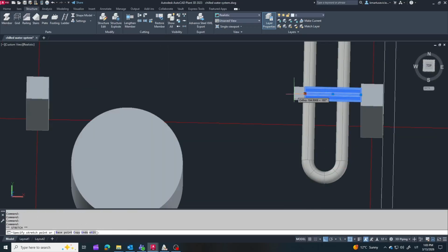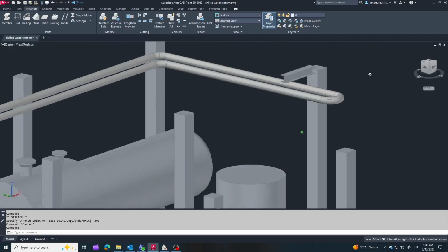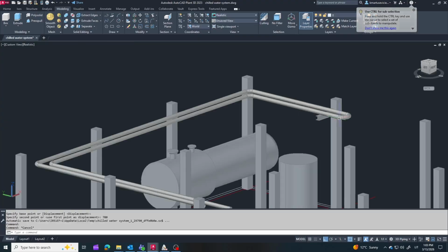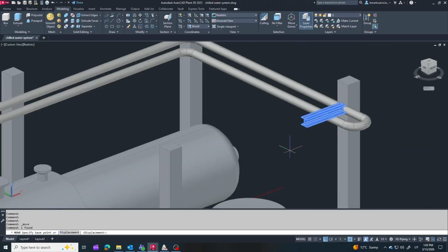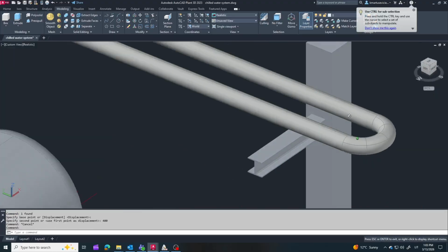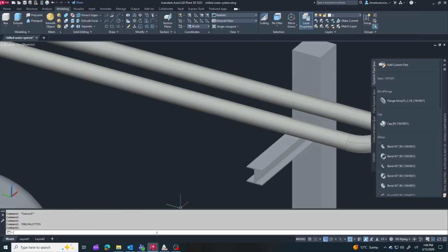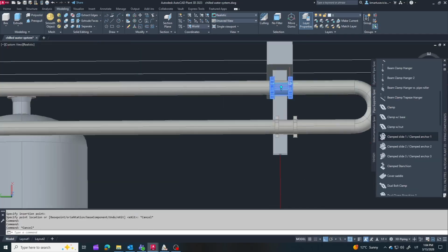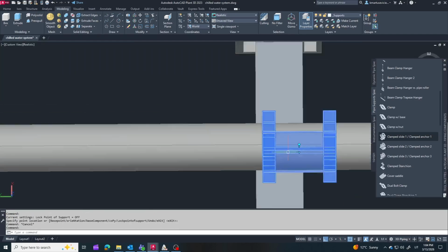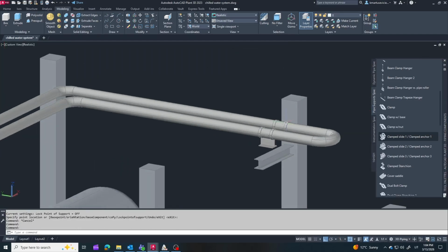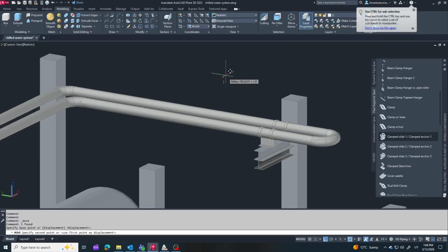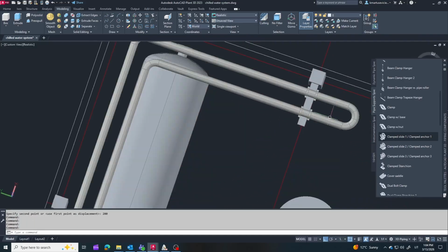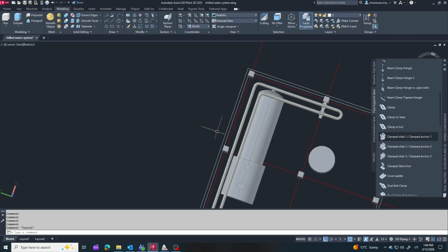For chilled water systems, several pipe materials can be used. In many industrial installations, carbon steel pipes are commonly used because they are strong, reliable, and suitable for larger diameters like the DN200 loop shown here. In some cases, stainless steel can be used, especially where corrosion resistance is important. For smaller systems or building HVAC installations, plastic pipes such as HDPE, PPR, or PVC are also widely used. The final material choice usually depends on factors like system pressure, temperature, corrosion conditions, installation cost, and pipe diameter.